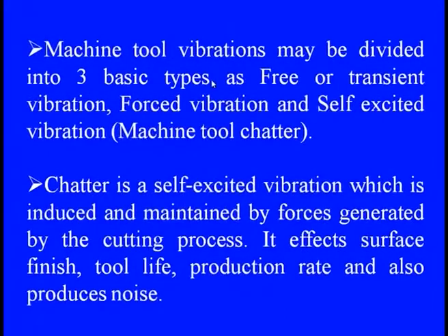And this chatter vibration straightaway affects the surface finish, because we want a surface finish at the microns level, which can only be achieved when you can control this chatter vibration. So, not only does it affect the surface features, but there is also a clear effect of this chatter vibration on tool life,